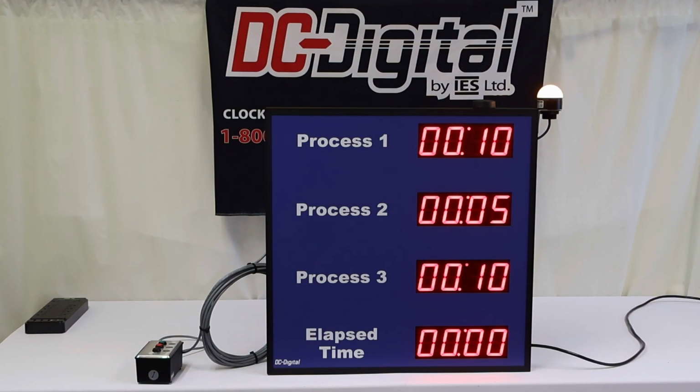Okay, so now that we have all 3 of them set up, we can go ahead and start 1. It'll count down from the set value as the elapsed time increments. As it reaches 2 seconds left, the Andon light will start to blink. As it gets to 0, the Andon light will go red, indicating there's a problem. The process continues to count and measure the time over, as elapsed time continues to elapse.